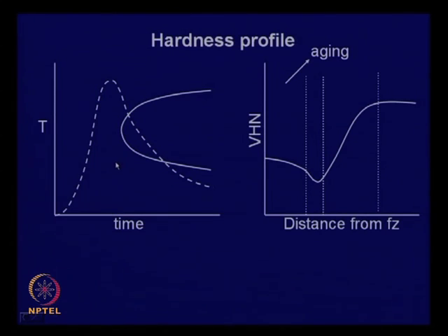For that you need to know the transformation diagram. Here also, as we have learnt, you have the C-shaped transformation diagram, a time-temperature diagram, and this is the C-shape where precipitation begins. Now, when you are heating, there is a heating time, and the temperature goes here, which is much above this, and you can call it the heat affected zone.